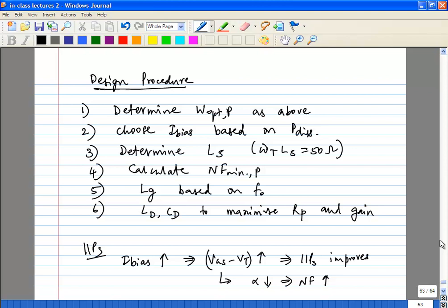When you are very close to the transmitter, you may not require so much gain, so you'll have gain steps from maybe 20 dB down to 5 dB or 3 dB. When you're closer, the signal is larger and you don't need such a good noise figure from your receiver. So once you detect such a large signal, you would automatically set your LNA to a low gain state.